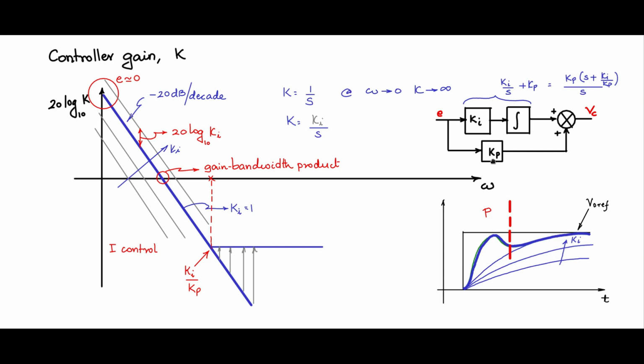So Kp also you try to increase from 0 onwards, gradually increase Kp. That keeps adding to the improvement in the dynamics, and then at some value you will see that it is best. Beyond that it will probably start to have damped responses, and you may have overshoots. Don't go over to that. You stop at the best response you think you can achieve by looking at the scope, and those values of Ki and Kp you plug in and you have your PI controller.